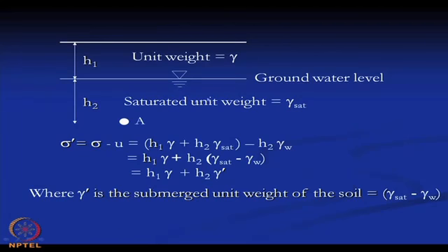Now, the total stress at a point can be calculated as H1 into gamma plus H2 into gamma sat,